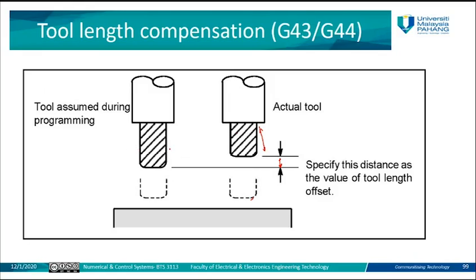So I am going to add some value in the Z axis, like a virtual or imaginary bar, a virtual extra length on the original tool. This will allow this tool to go down deeper for this part. In actuality it's short, but in the program I will consider it deeper, so the spindle here will move depending on the program value.